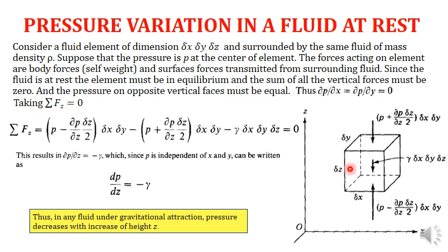is equal to 0, meaning in the vertical direction, only one direction is enough, because this is a very important direction in which the weight of the fluid is also included. In the x direction, usually we can consider it also. It is going to give you the same result, but preferably we consider the y direction because it includes the weight also. And we can also relate our weights with the specific weight gamma with respect to the pressures, and give some relationship of those.